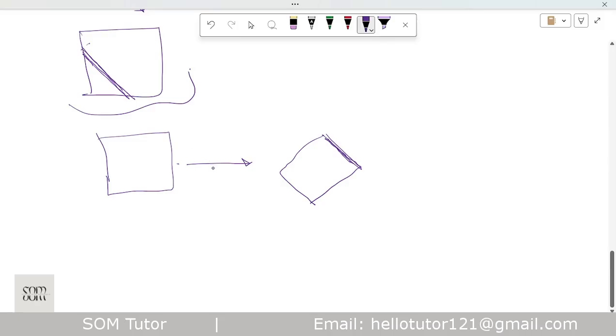This is just one way of perceiving it. The other way, if you don't want to say, "I am rotating all of this," is that you can simply assume this is one normal plane, this is another normal plane, and this one is the oblique plane, and I have to find the stresses on the oblique plane. I know the stress on this normal or horizontal plane: tau 2 and sigma 2.